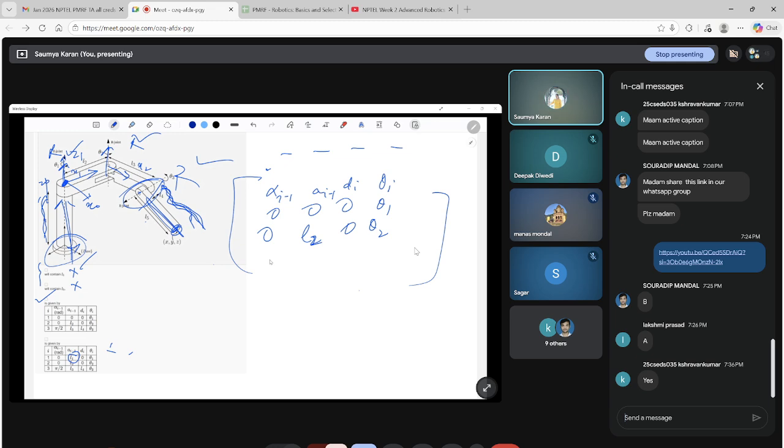Now, let's talk about this joint. It has the axis pointing in this direction, which is perpendicular to the axis here in this case, right? The axis is perpendicular to that of joint 2. So pi by 2 would be the angle between the z axes. The distance between the z axes is given by L3, because this is the difference.